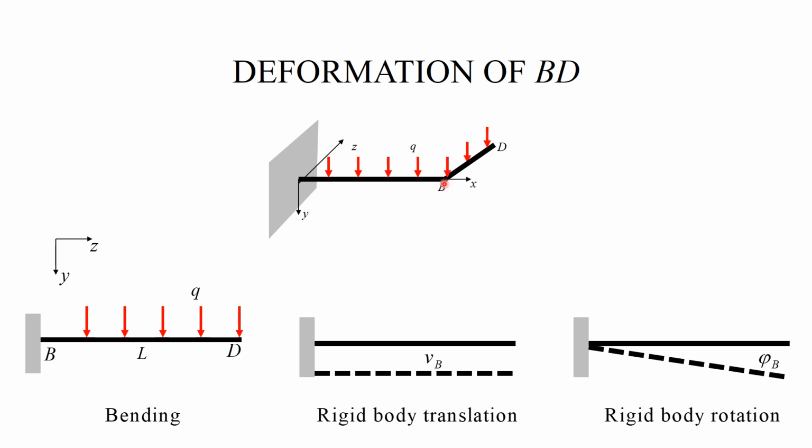Because the point B moves, and that's VB, plus the twisting angle at B, when we look at OB, translates into a rigid body rotation of BD associated with bending, and that's how it's shown. Right, so this is phi B, and this phi B is because the beam OB twists.